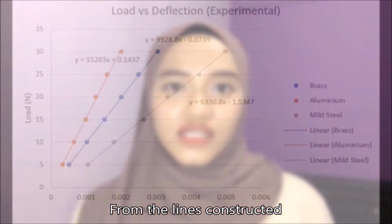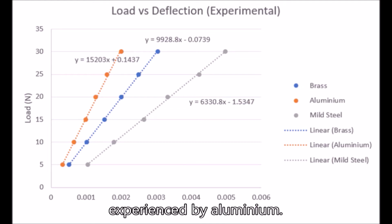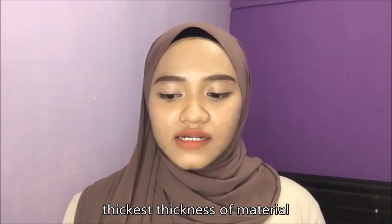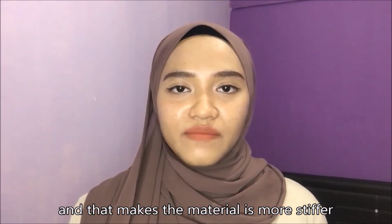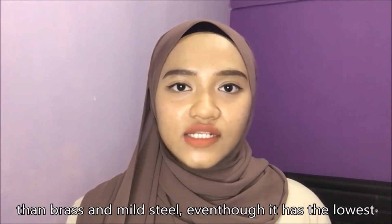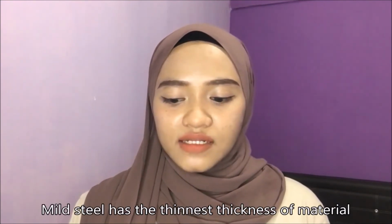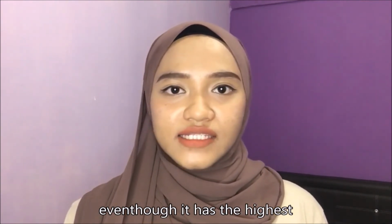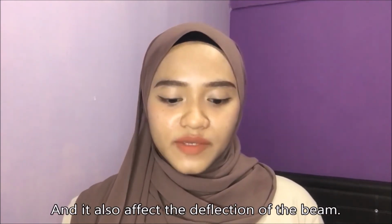From the lines constructed, we can say that the least deflection is experienced by aluminium. This is because aluminium has the thickest material among all, and that makes it stiffer than brass and mild steel, even though it has the lowest value of Young's modulus. But the maximum deflection is experienced by mild steel. Mild steel has the thinnest material, even though it has the highest value of Young's modulus, and this also affects the deflection of the beam.